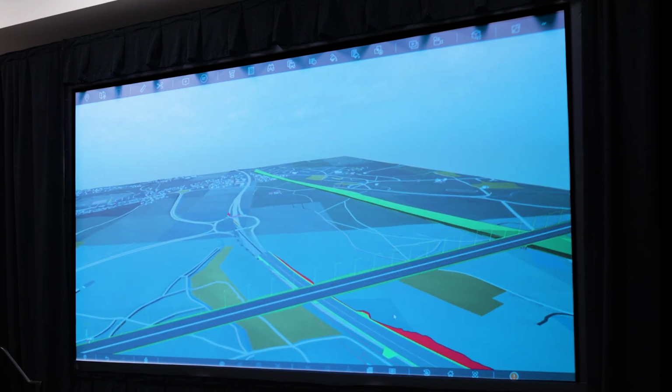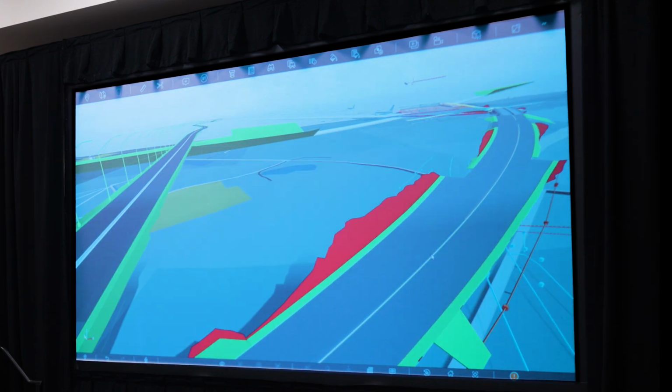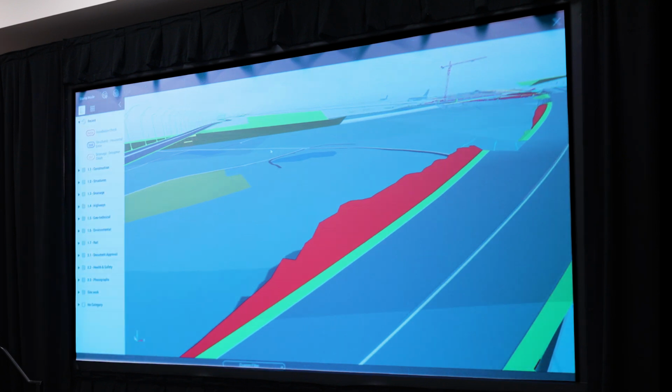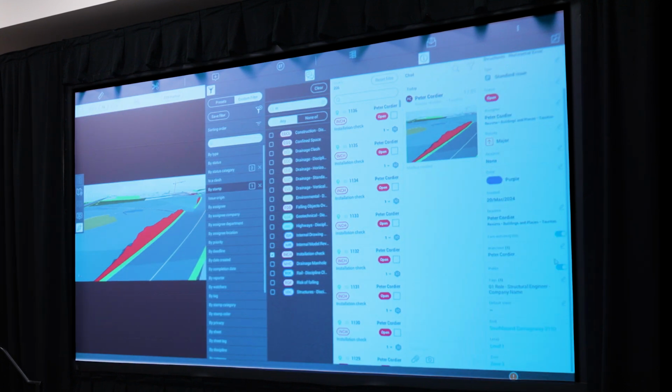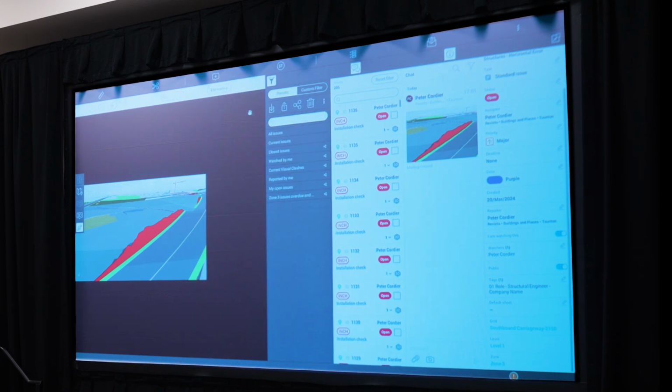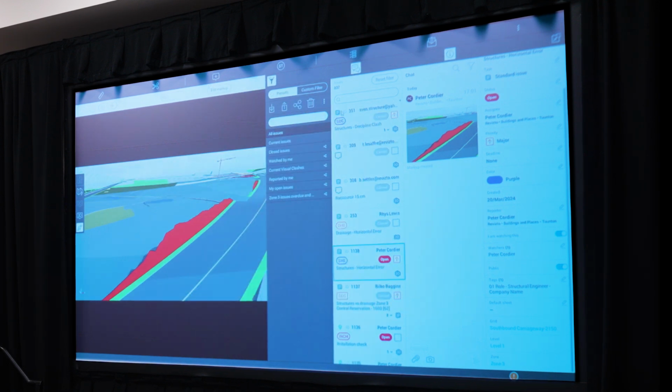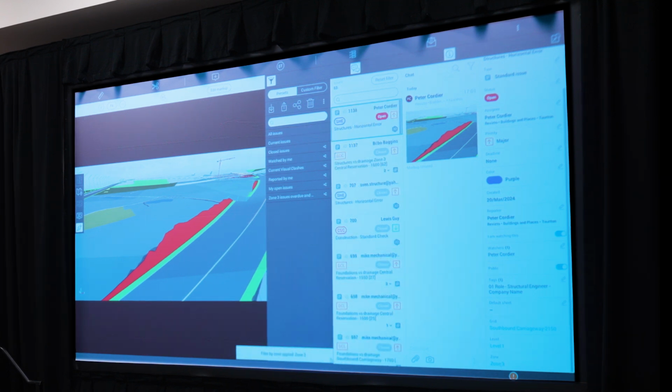So just create an issue. I think there's a zone in there somewhere. It doesn't matter what type of stamp I use. So yeah, I've just created that issue, and you can see Revizto knows where it is, including which zone it's in, and you can very easily filter. If I filter all of my issues, 837, and then click on that piece of metadata, you can see it's automatically filtered everything that's in zone 3.